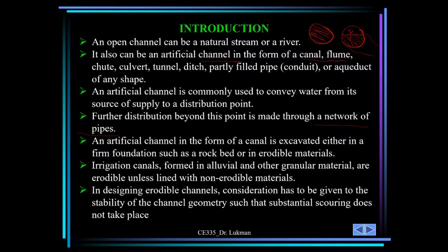In designing erodible channels, consideration has to be given to the stability of the channel geometry, such that substantial scouring does not take place. When you have a rectangular channel, if it is dug in sand, there is a tendency when fluid is flowing that it may eat away the side. It will be expanding, eating away the side, and carrying along the eroded debris with the flowing fluid. So we need to ensure scouring does not take place.